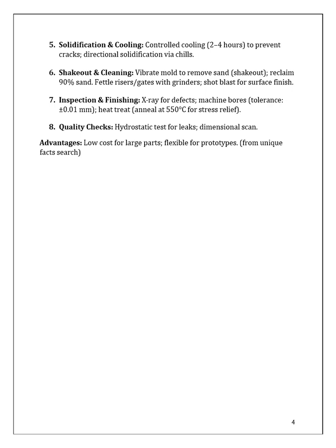Solidification and cooling. Controlled cooling takes 2 to 4 hours. There are some cooling methods you can use, but there are limits of 2 to 4 hours. Then shakeout and cleaning: remove sand 90%, finish by fettling, inspection, and X-ray for defects, and machine bores 0.1 to 0.5.